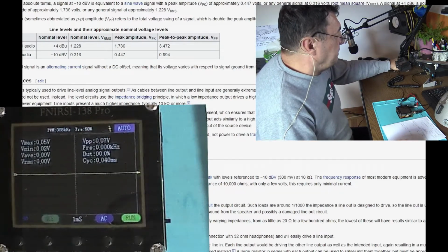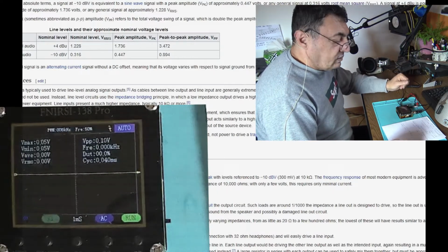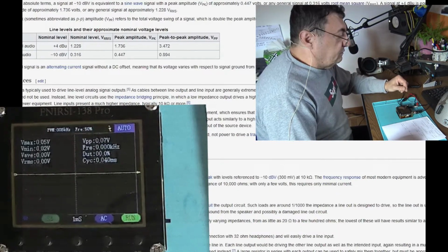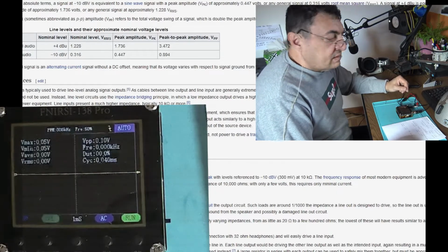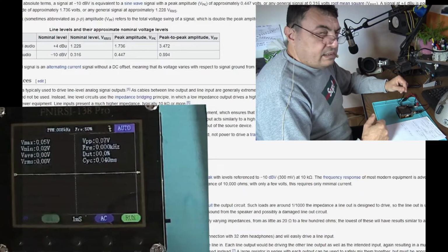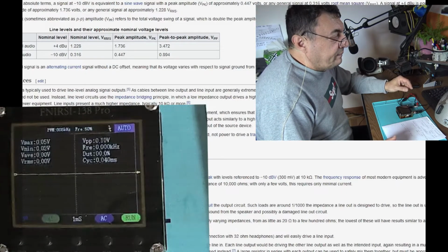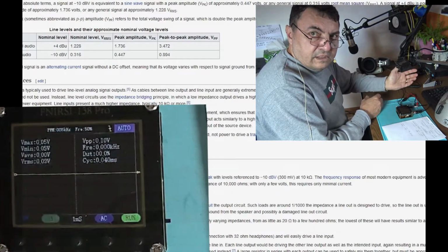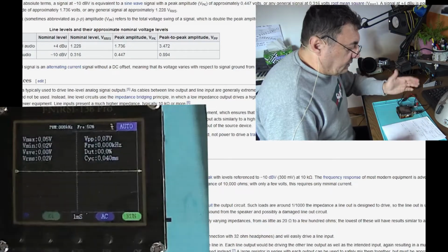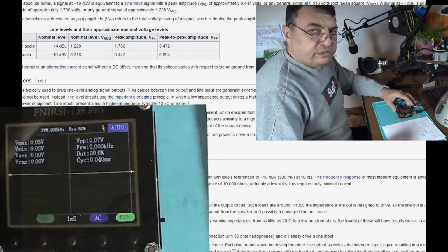So far what I found is that a mobile phone or MP3 player or any small device like that doesn't have enough power or level, let's say voltage or dBs, decibels, to have a proper signal for a power amplifier. All we need is a preamplifier, at least 10 times preamp, which takes the low level signal and amplifies it to a certain level to have the maximum transfer and a proper wattage or power output from the amplifier.